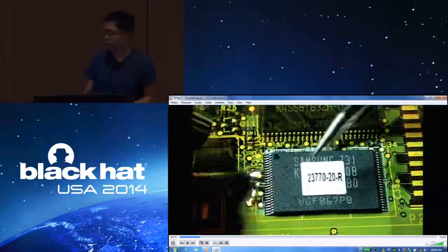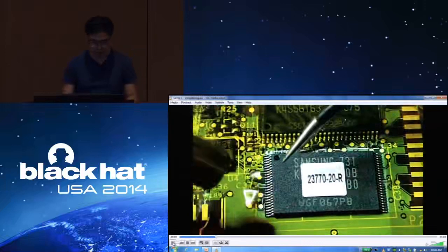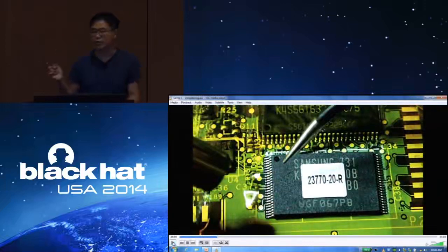So you can see this. Just before this, you saw that the temperature was 330 Celsius, around that temperature. Actually, that is the temperature you use for soldering with the iron, when you are using soldering irons for soldering. So I was just using the same temperature for desoldering. At that temperature, the solder is supposed to melt away.